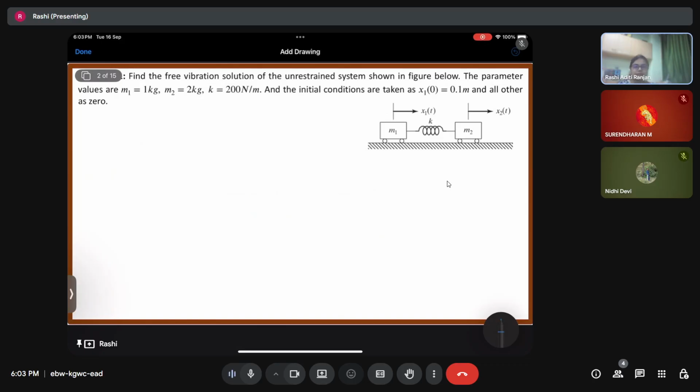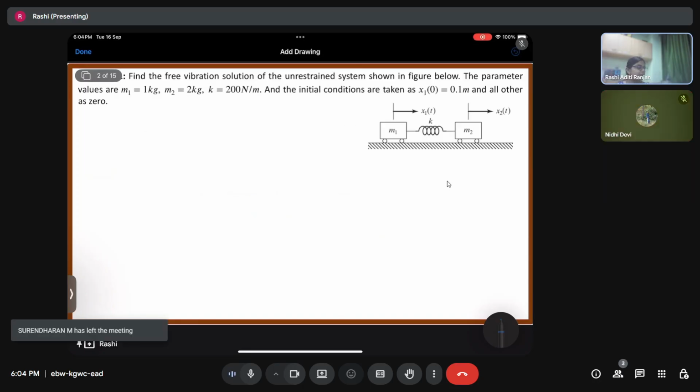So the basic concept that we discussed last week was how do we deal with a 2 degree of freedom system, or basically a multiple degree of freedom system. We learned how to derive the equation of motion, how to deal with the modes and mode shapes, and what the general solution of the system is, which will be the amalgamation of the two modes of the system. This week it is mostly concerned about how the 2 degree of freedom system essentially works as vibration absorbers and tuned mass dampers, depending upon how we apply or use the second mass and the second stiffness.